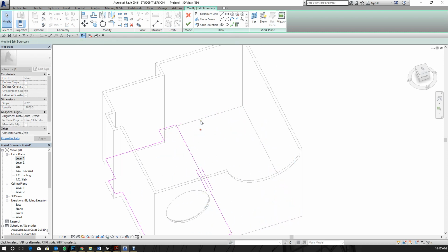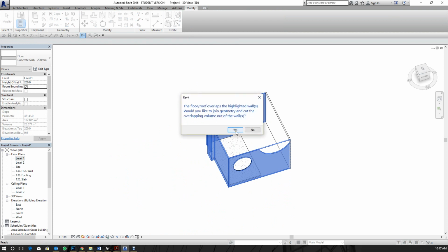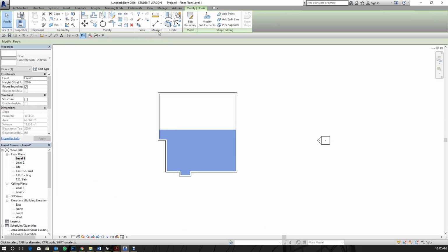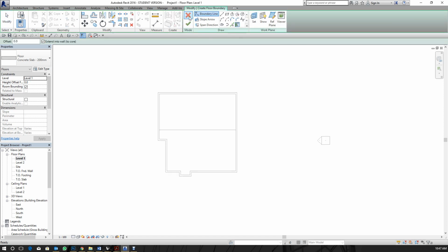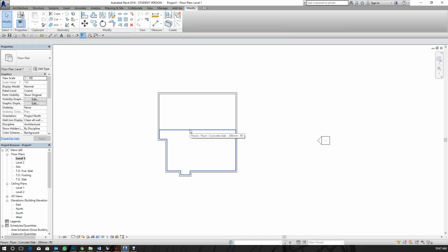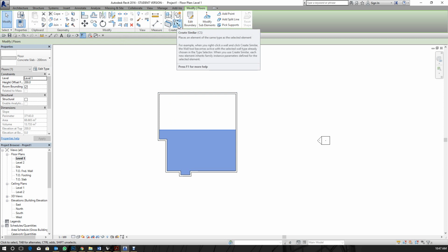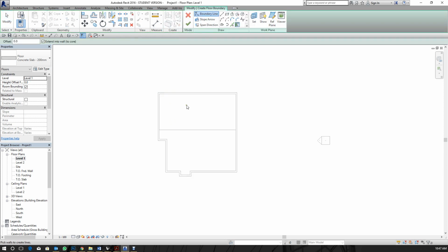and let's say, let's go back to plan view, that's one floor, and I had another floor. Oh, and just not to skip, if you want to create a new floor and you already have an existing floor selected, you don't need to go back to Architecture and Floor and all of that. Just select that floor, and on the ribbon at the top, you would see the Create Similar icon. Just select that, and it automatically takes you to the floor mode.